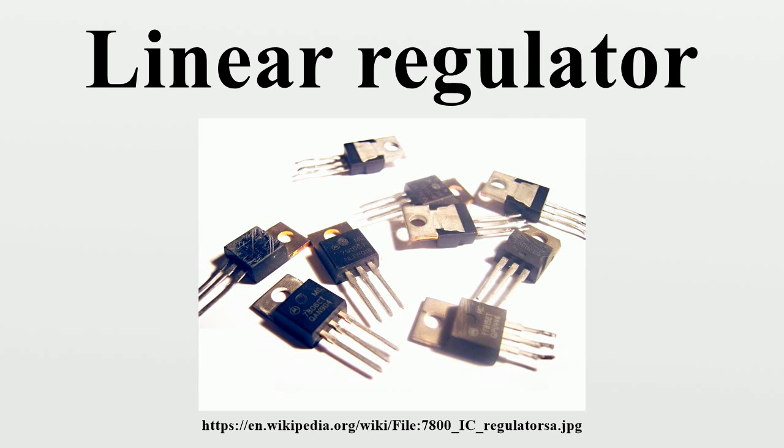Linear regulators can be constructed using discrete components but are usually encountered in integrated circuit forms. The most common linear regulators are 3-terminal integrated circuits in the TO220 package. Common solid-state series voltage regulators are the LM78XX, LM79XX, and the AMS1117 series. Common fixed voltages are 1.8V, 3.3V, 5V and 12V.